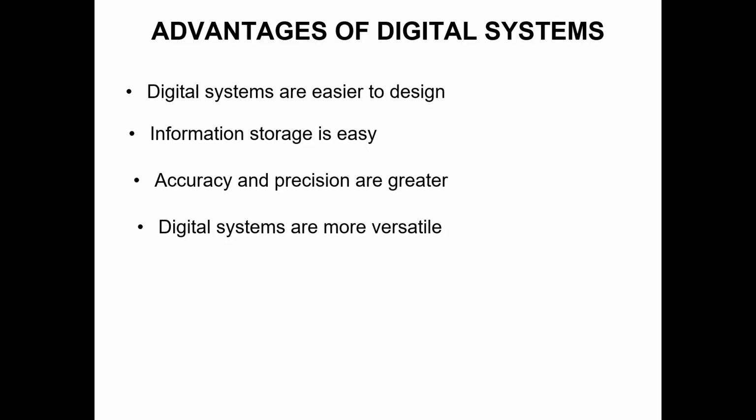Even though analog systems can also be programmed, digital circuits are less affected by noise. Unwanted electrical signals are called noise. Noise is unavoidable in any system. Since in analog systems the exact value of voltage is important and in digital systems only the range of values is important, the effect of noise is more severe in analog systems. In digital systems, noise is not critical as long as it is not large enough to prevent us from distinguishing a high from a low.